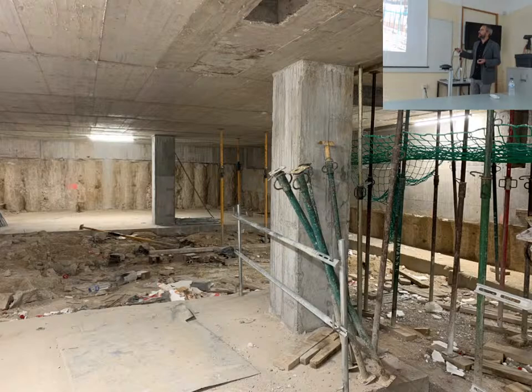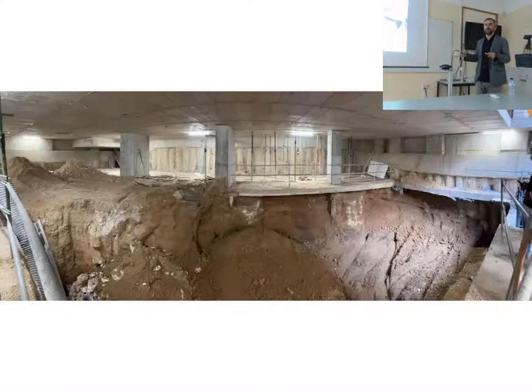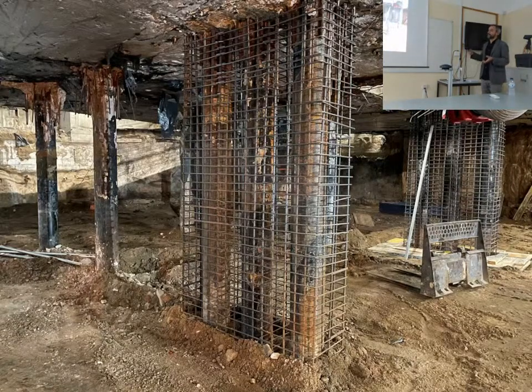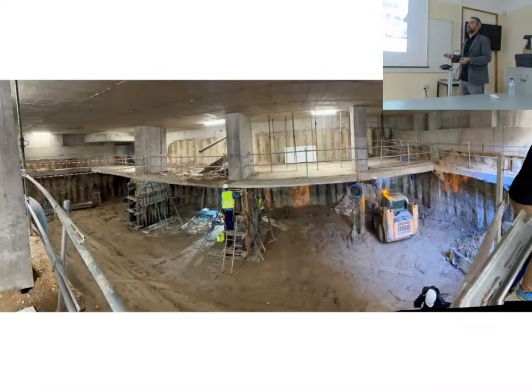But then this is the -1 level, and we are now excavating below at the same time, excavating under the building that is in the process of being constructed. Okay? So once we remove the soil of one level, we introduce the reinforcement, we pour the concrete, and we continue, also pouring the next slab and continuing going down. With this, the point is that they finished the structure of the upper levels, and it was possible to continue with the installations and with the finishes at the same time that we were finishing the structure of the parking. That is more time consuming because of the soil.